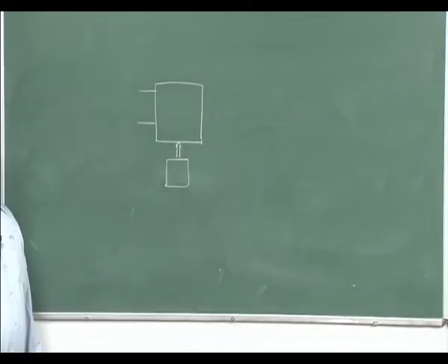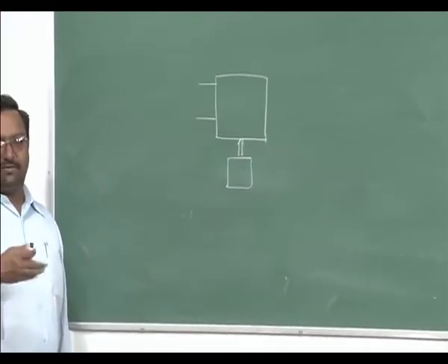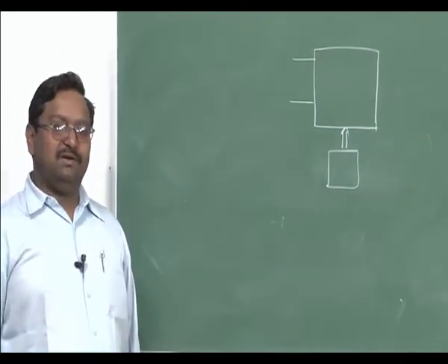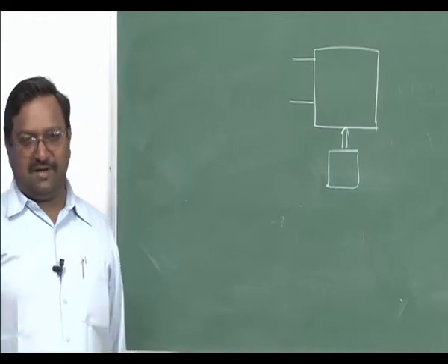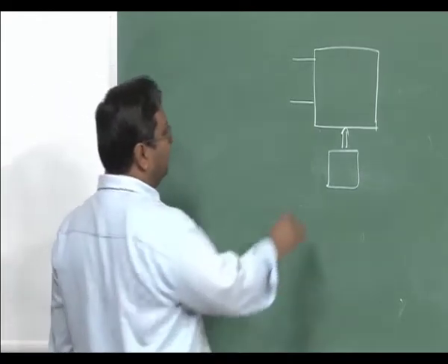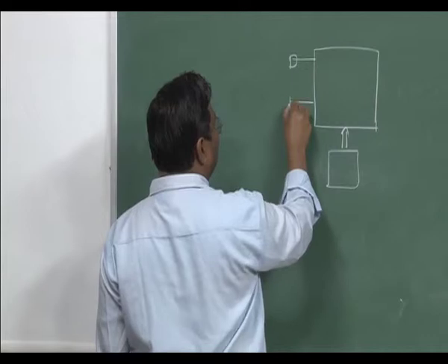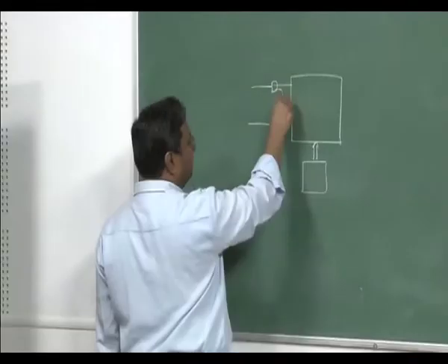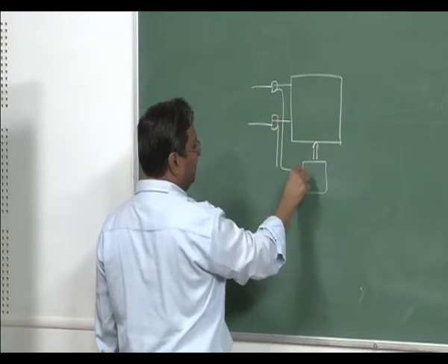In fact, I can make a parallel interconnect and keep sending the control bits one by one separately as a parallel line, or it can be attached as a tag in front of the packet. If it is attached in front of the packet, you require an interface processor. It receives the whole packet, gets the tags out. These tags are sent to the controller.